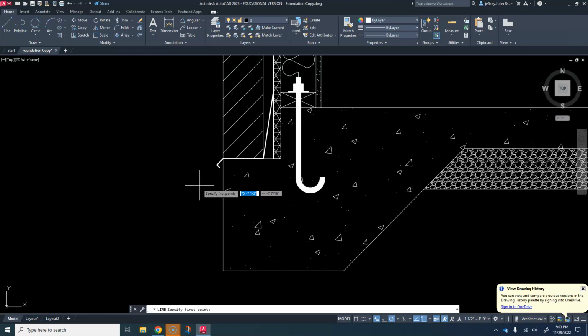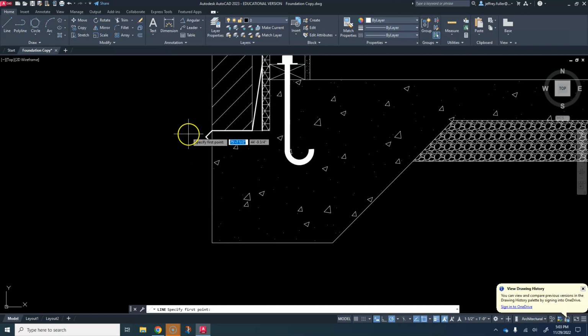Earth, the ground has to, there has to be at least 4 to 6 inches of exposed concrete above the ground before you actually get to your wall finish. At least that is the code here in Texas in most places. And because we have a brick wall, we're only required to have 4 inches of exposed foundation before the earth begins. If you had wood siding or something like that, then it's 6 inches. But for bricks, it is 4 inches.